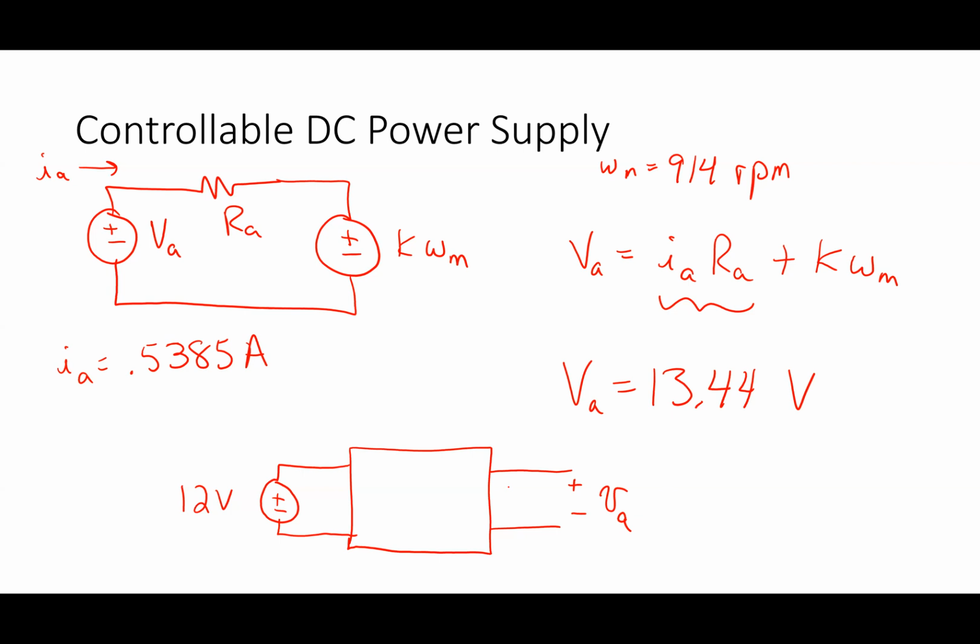Can I use a transformer? Well, yeah, you're jumping ahead of me. He's going to PWM. That's what we're going to do. Why don't I use a transformer? Isn't a transformer simple? Why can't I use a transformer to do it? It's DC. Well, so what's wrong about that? There's no changing magnetic field that comes from DC. In other words, if I put 10 volts DC on the primary side of a transformer, how many volts do I get on the other side of the transformer?